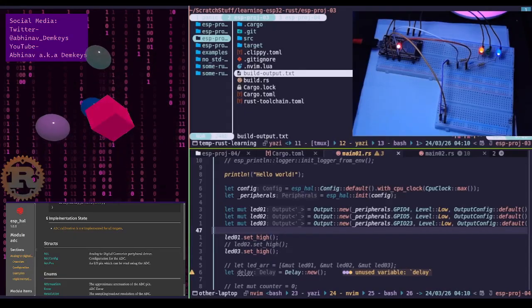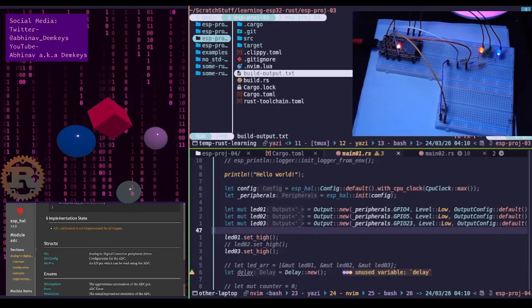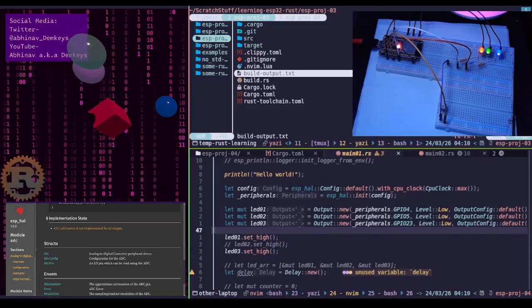Basically we are taking the two points from point A, which is our ground voltage and the corresponding digital reading, and point B, which is our 1.0 volt source and the corresponding digital reading, 1242.